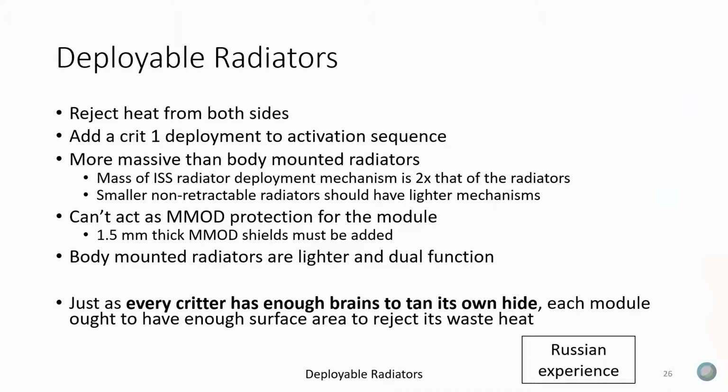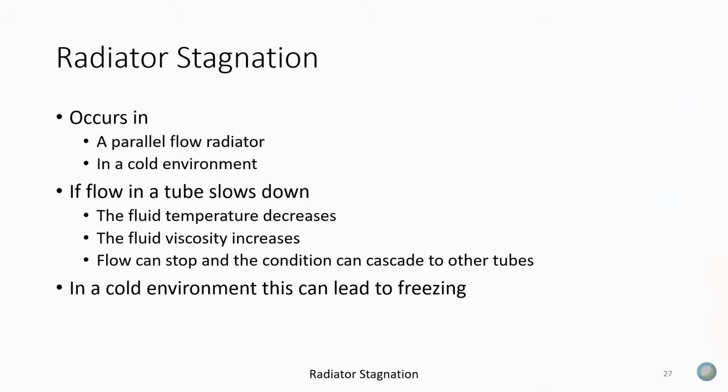We moved away from that with space station, partly because our radiators were built for 75 kilowatts of heat rejection, and you couldn't do that with the smaller modules, which were also partially blocked by the adjacent modules and by the truss. But as it turns out, we've never used all the capability on space station. We run it at somewhere around 30-some odd kilowatts. And so we possibly could have gotten away with body-mounted radiators.